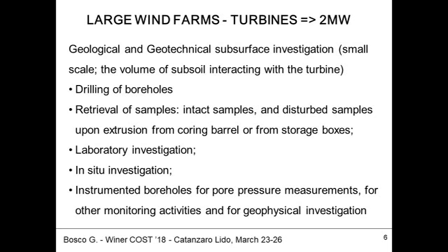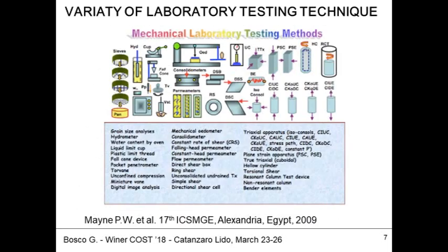Subsurface investigation is usually carried out in this area through drilling, and calculations are based on data retrieved from laboratory tests on soil samples, disturbed or relatively intact, due to the typical layering. In situ investigation is usually not possible. We now have an overwhelming variety of laboratory investigations, and I have here a collection of some.